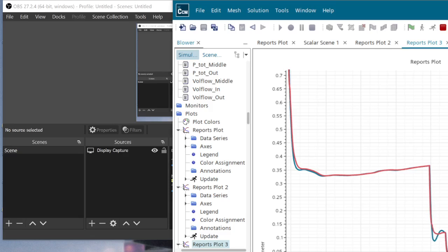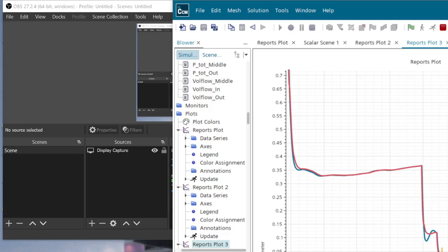None of the above? So then instead of multiple fan curves, one for total pressure and static pressure, both be... Right, so you'll have at least two of these graphs. One will be total pressure. One will be static pressure. So you will have effectively two graphs. One which will have the y-axis of a change in static pressure, and then the second one is a change in total pressure.